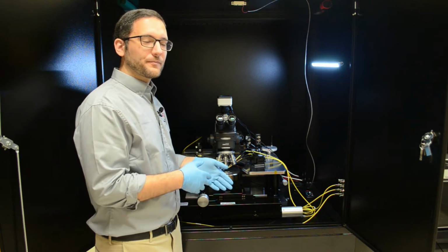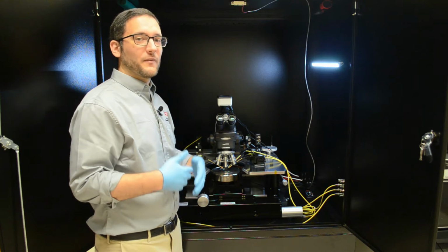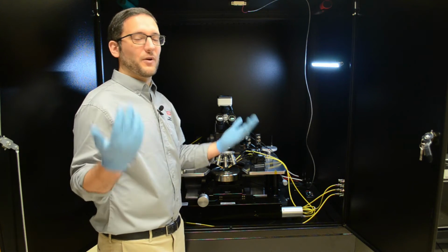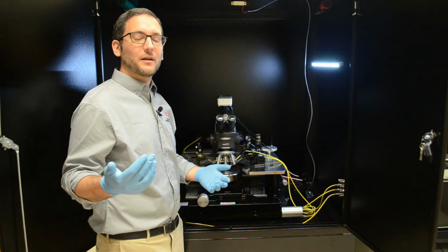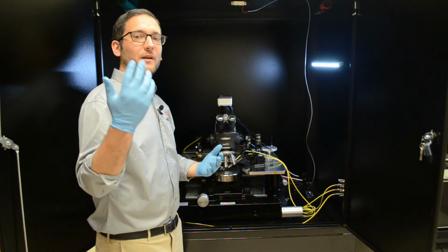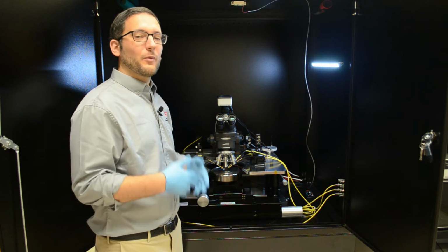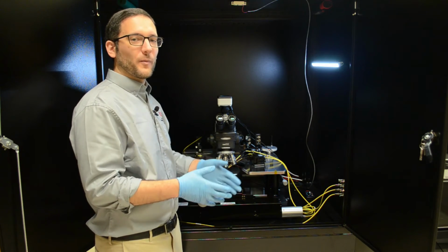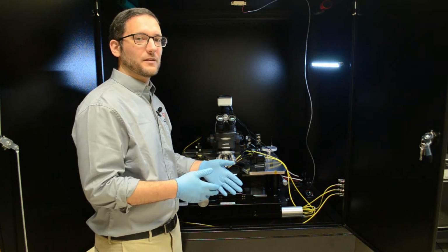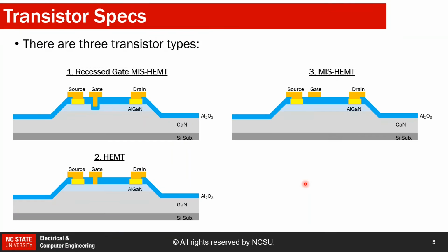the device. Noise can come in the form of electromagnetic noise that's present in the air from your cell phone, for example, or a base station that's nearby. But it can also come from ambient light that might interact with your device. We want to try to isolate these variables so we can really look at the intrinsic performance of the semiconductor devices that we're testing. In today's demonstration, we will be measuring the IV characteristics of AlGaN-GaN HEMTs on silicon.